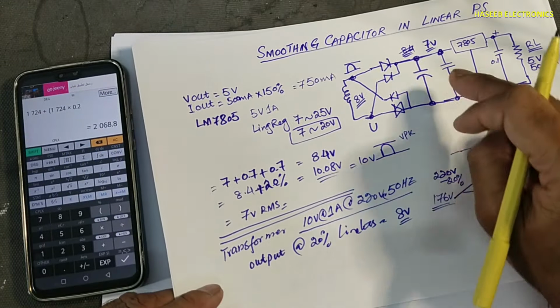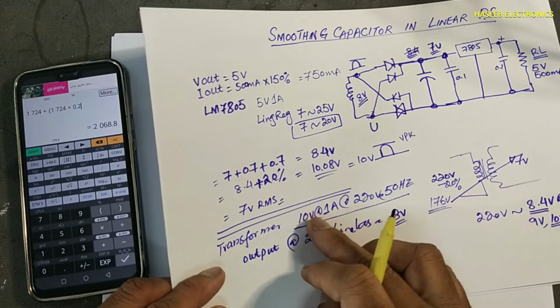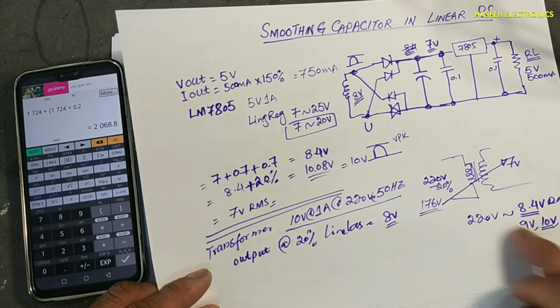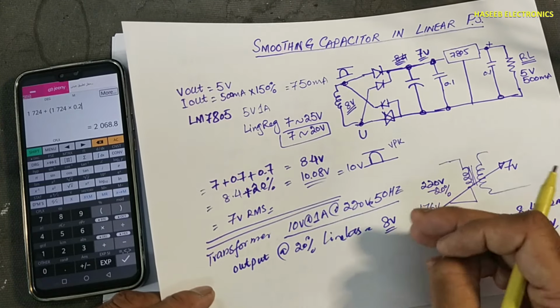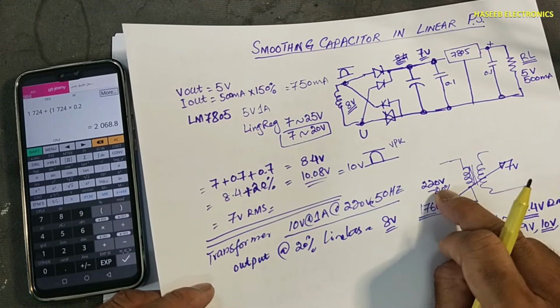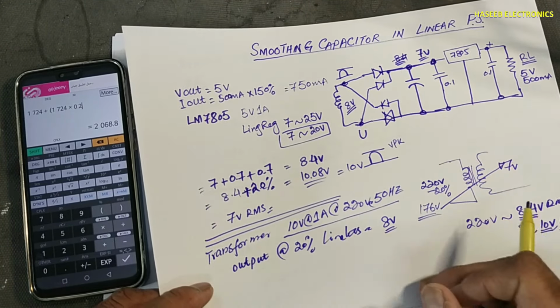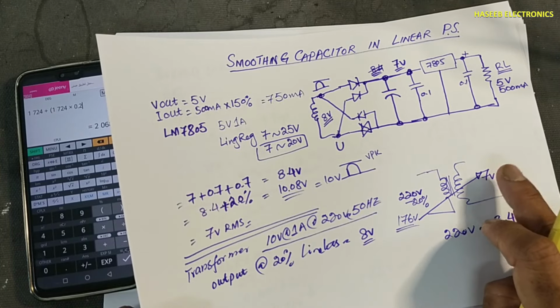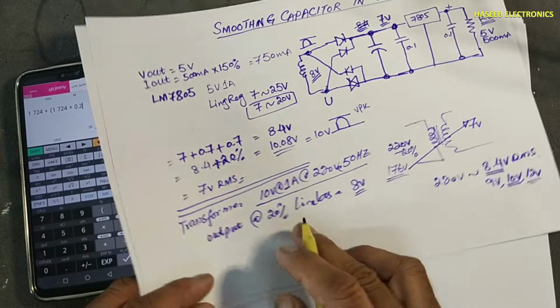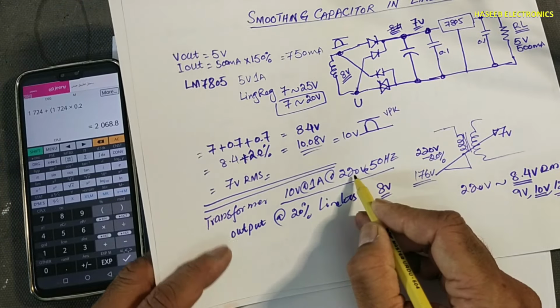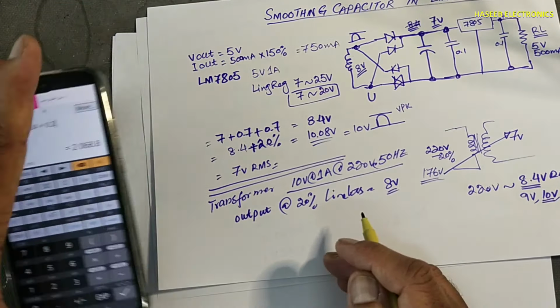Now when we are calculating a capacitor, we need to check voltage. Here we calculated capacitance considering the low voltage, but in case the line swells 20% above 220 volt, similarly the voltage will increase at the output. We calculated this for 10 volt at 220 volt.